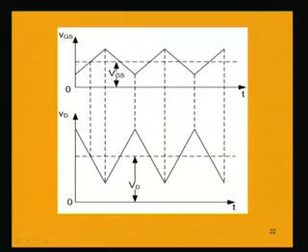So, this constant voltage capital V capital GS is the DC biasing voltage between gate to source. This will be present. On it is superimposed a small vgs, and the instantaneous value of the voltage between gate to source is capital VGS plus small vgs.